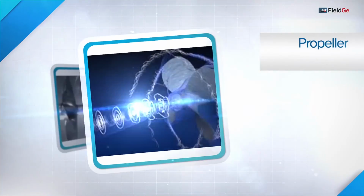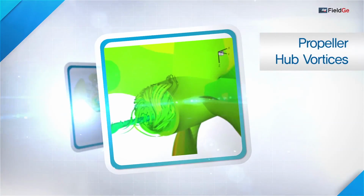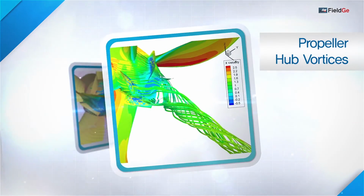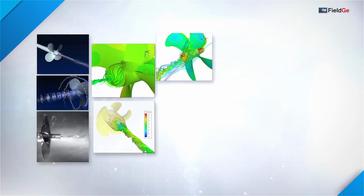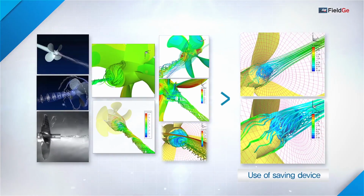These are examples of hub vortex. The hub vortex is formed by the combination of the individual vortices shed from each blade root. Illustration of a case of attaching the reduction device is on the right hand. While the propeller is rotating in the clockwise direction, it normally causes the flow to also be in a clockwise direction. However, the direction of flow can be controlled due to the device.